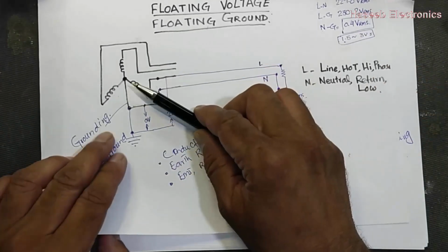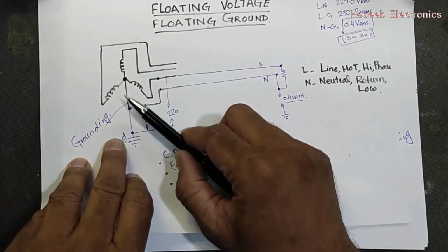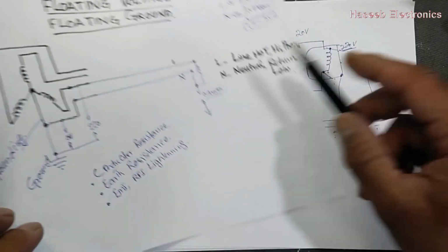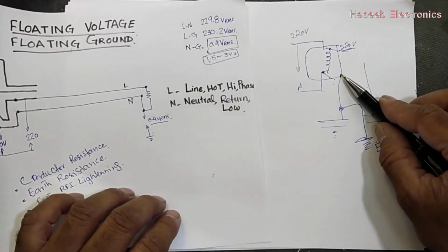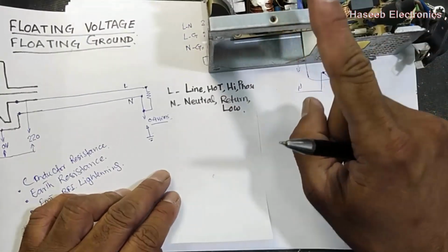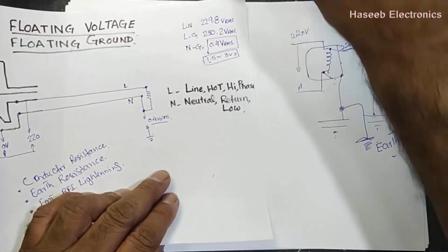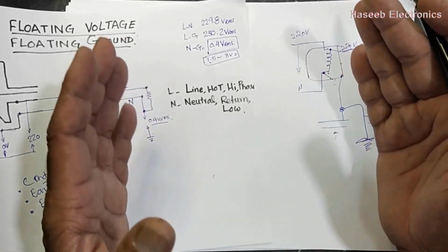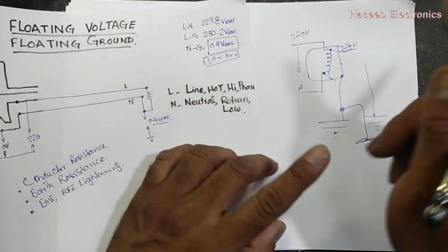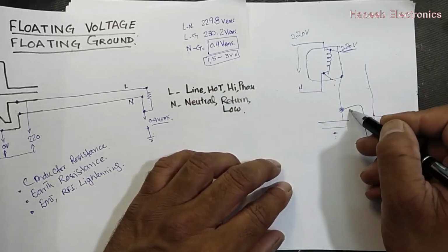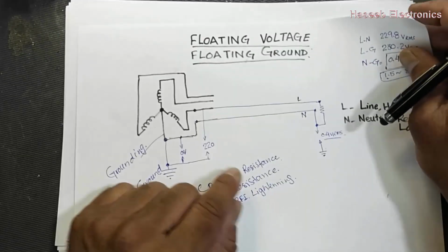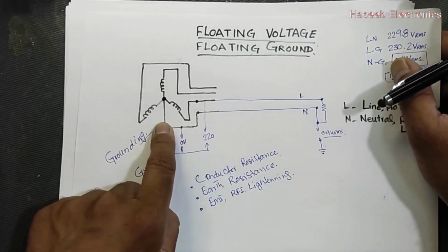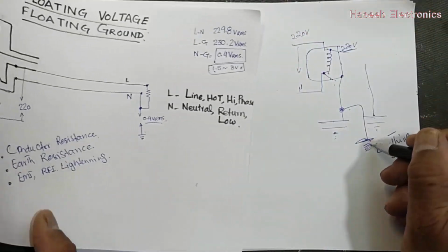If we connect the neutral line, the low-side current-carrying conductor, to the ground, it is called grounding. And if we connect a dead metal part, that is the chassis of this power supply or the stand of a pedestal fan or any washing machine which has a metallic body, to earth, it is called earthing. In this condition, the earth is not directly involved in the return path; it is there for safety.